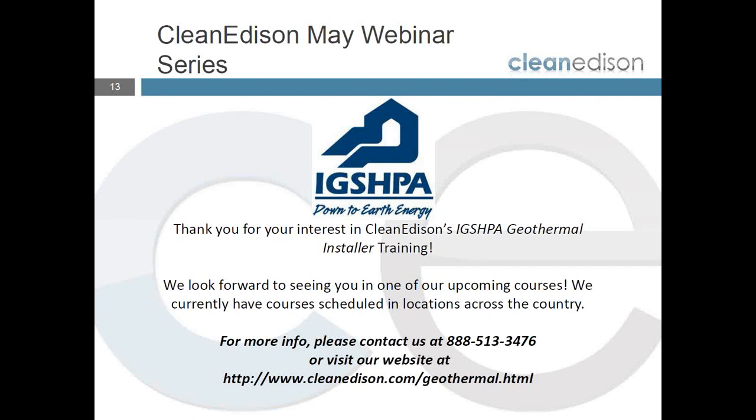For open loop, there are some different characteristics. Long Island, for example, has a very sandy geology, and they actually can pump water up one well and reject it into another well, and that well can accept it. For areas in the country where you have ledge rock or clay soils and the ground cannot absorb all of the water, it pays to go with a closed loop system. But as we said in the slide, it all depends on the geology and the climate,